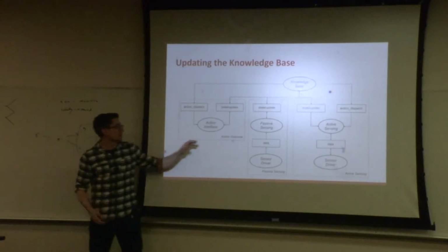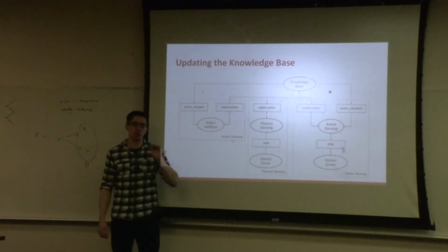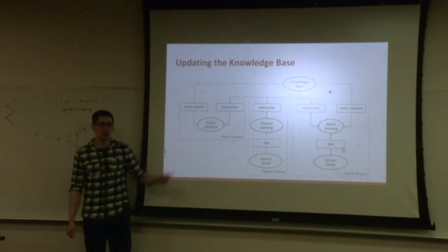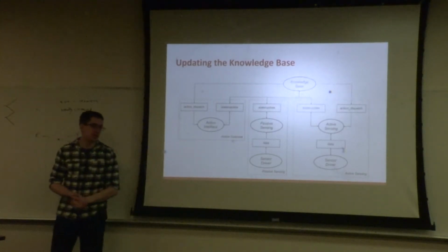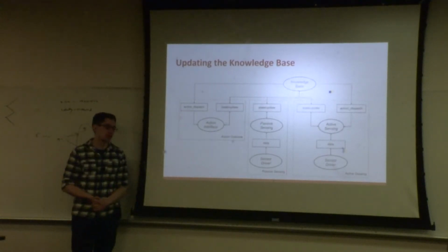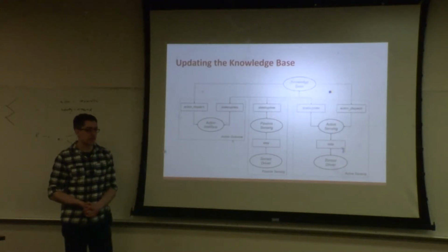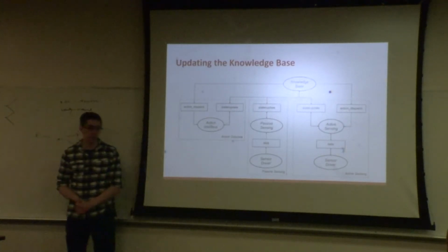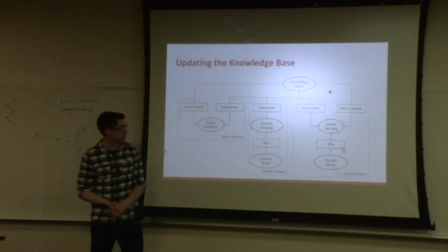In an ideal world, every part of the state would be covered by only one of active sensing, passive sensing, and dead reckoning. And if you can keep it that way, then you're solving a nice problem. And it also presumes, as far as the sensing side of things, you're translating a complex world model or data, interpreting that through some kind of model to abstract, like a fact, like being at waypoint 1. You have to define what waypoint 1 is. It means within the radius so much, compared to your coordinates that you're actively moving, for example, or deciding whether something's open or closed.